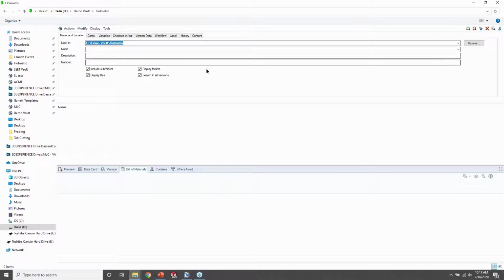So when you're searching in PDM, the great thing about PDM is it searches quick. So even if we're searching for something like file name, it's so much more effective than Windows Explorer. And really the reasoning for that is because Windows Explorer kind of relies on Windows indexing. And even if I know the name of a file in Windows Explorer, knowing the name of the file doesn't necessarily mean that you're going to be able to find it fast. If you try to search the top level of a folder structure for a file name, it can be a while, especially for companies that have accumulated a large amount of data.